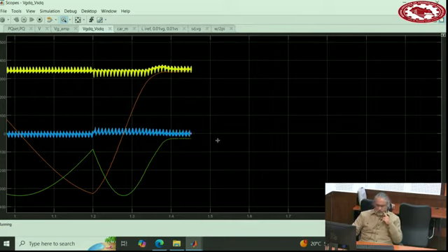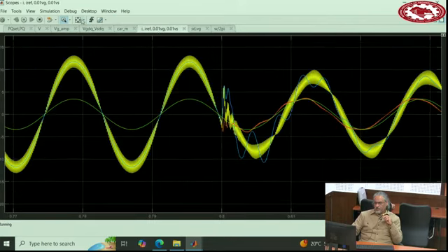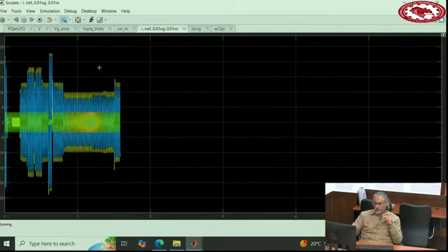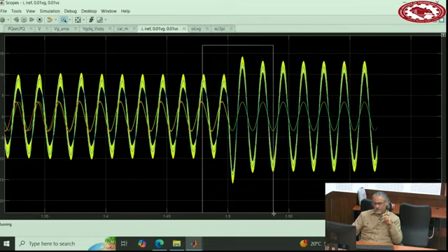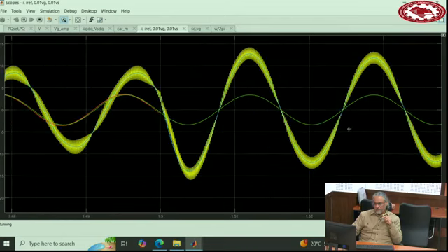And now when you are sufficiently close, here you can close the switch and connect to the grid. So the voltages become exactly equal, and the transition should be good. So this is the transient that you get at the transition. Yeah, very smooth.